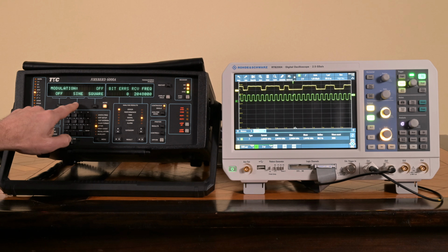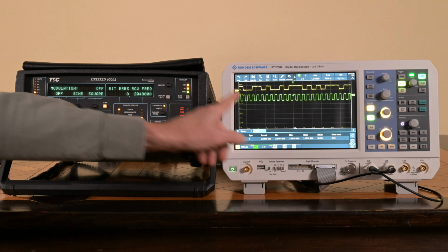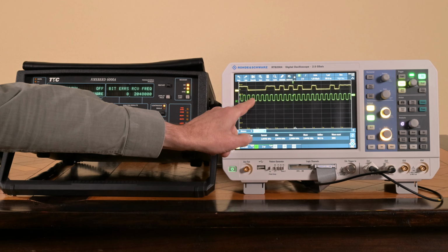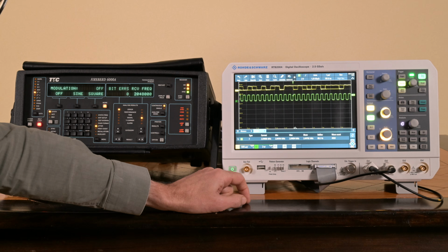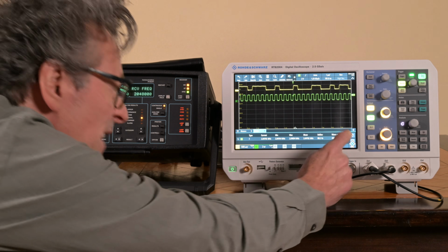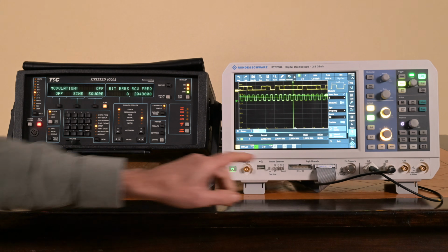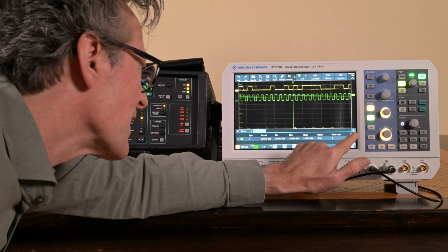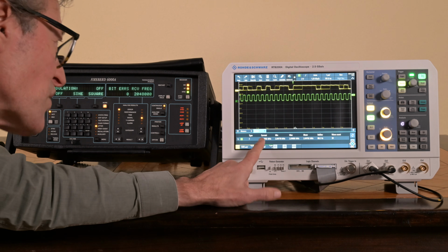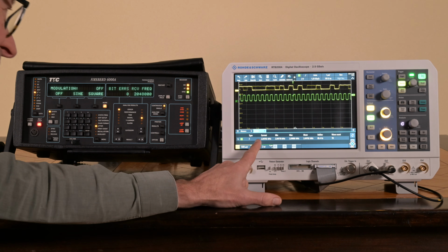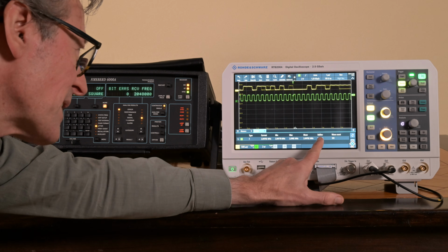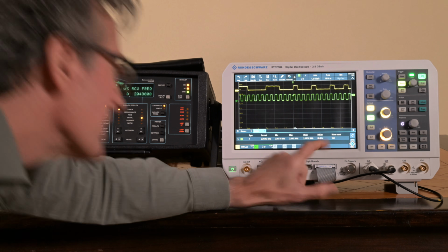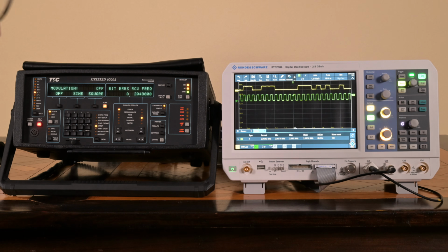So let's turn it to a sine wave. Before I do so, I see that my clock signal here on the oscilloscope is a very tight clock signal. Let me reset my device statistics. When I'm not sitting right in front of the device, I often misclick. So we see exactly the clock frequency we're expecting, and we got a standard deviation of 19 hertz on 2 megahertz in total.